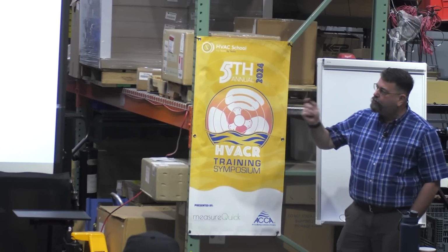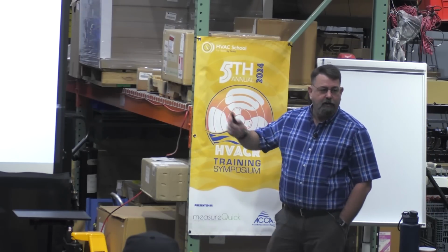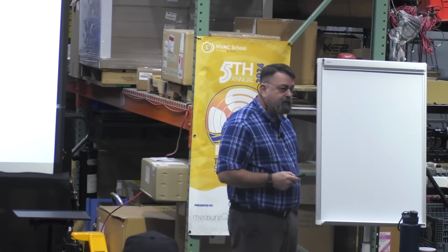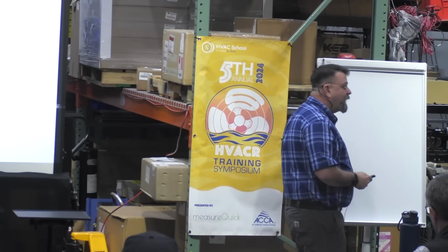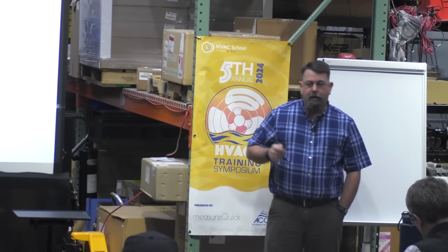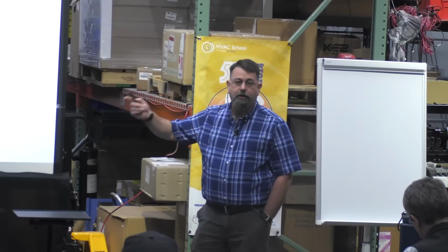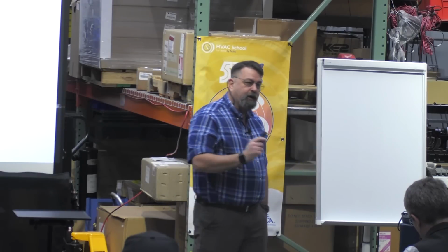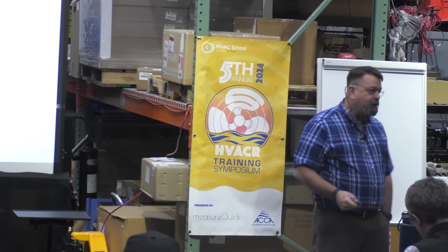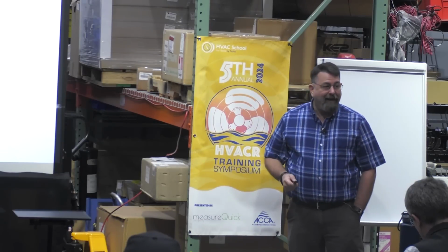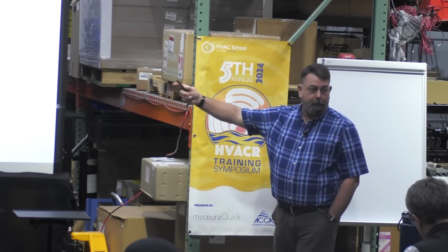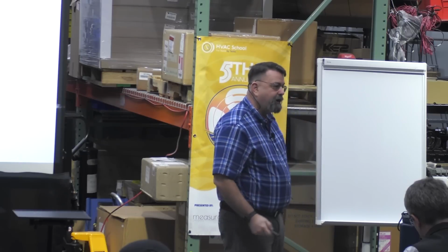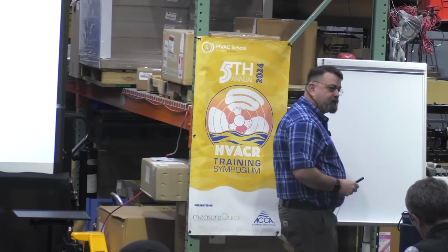So I don't know by eyeballing this whether it's flooding or not, right? So that means I'm going to be very proficient at taking superheat. In fact, my computer is going to be measuring those values for me, so I can just go in and take a look. I'm going to have a temperature probe on my main suction header. I'm going to have a pressure probe on my main suction header. That's what's telling my compressors to come on and off, right?